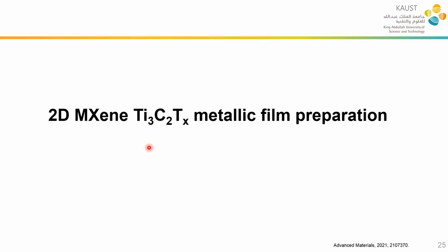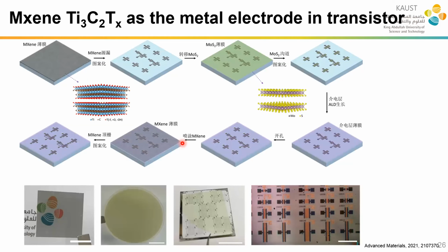But if we really want to achieve this goal, we need to first prepare a good film. So my research initially focused on the preparation process of Ti3C2 MXene, titanium carbide thin film. Actually, MXene thin film preparation can be easily done by spray coating. Our exploration here is not just the thin film preparation; it is to confirm whether this thin film is compatible with the nanofabrication process.